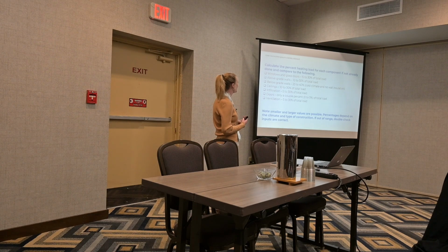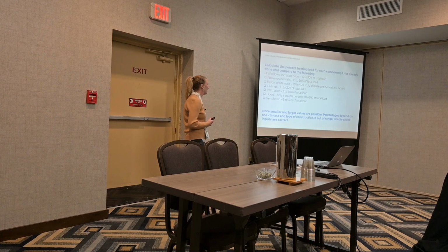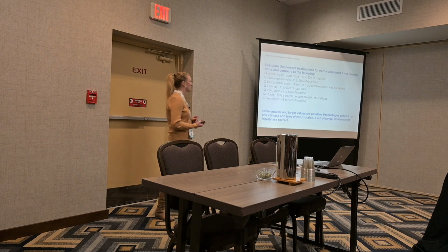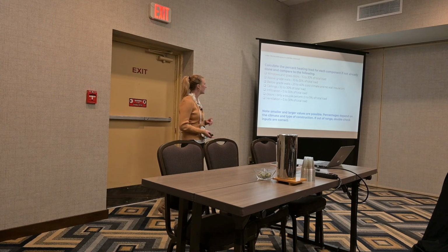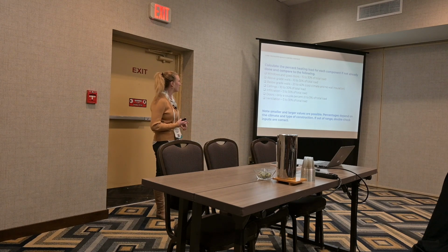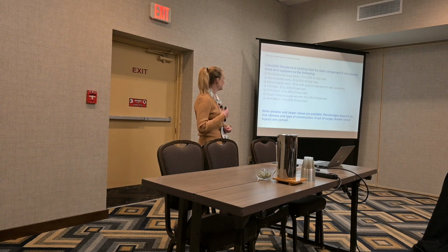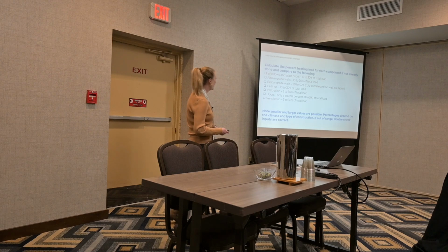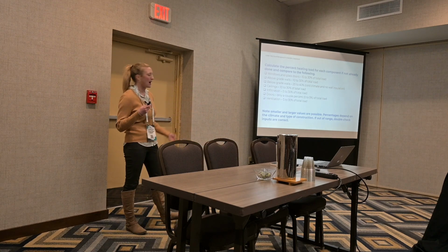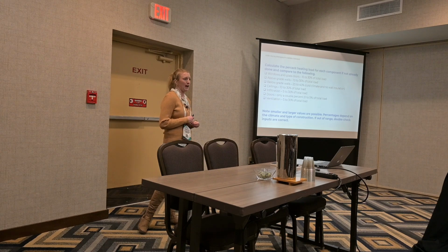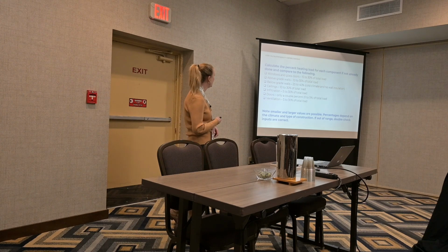Are the windows and glass doors within 15 to 30% of the load? Above grade walls within 10 to 30, below grade walls 20 to 40, ceilings 10 to 30, infiltration 5 to 30, doors only going to be a couple percent, and ventilation 5 to 30. Again, percentages depend on the climate and type of construction, but these would just be red flags if anything's out of range.